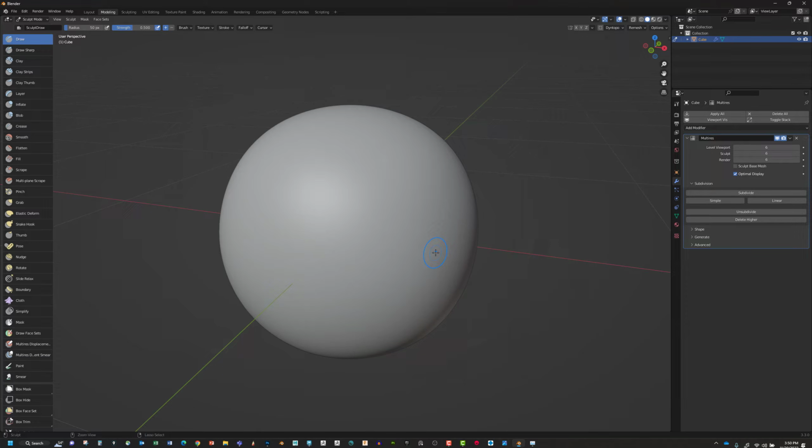I'm going to hit undo multiple times. The other thing is if we want to sculpt with symmetry, we can turn symmetry on like this. Because we're in a sculpting mode, a different mode, we don't have access to our quick favorites anymore. So let's right click and say add to quick favorites, and now I can tap Q and turn symmetry on and off right under my cursor. And if we want to change the brush size, just tap F and drag left or right, and that's going to control the size of this.